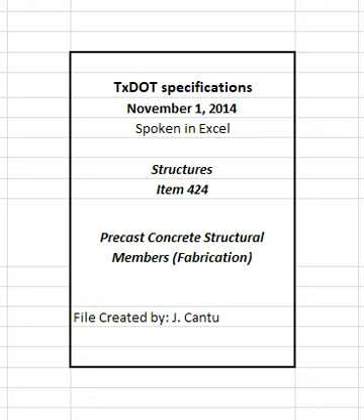4.2.7.4 Accelerated curing. Accelerated curing is defined as curing with artificial heat provided to the curing enclosure or forms. Test accelerated curing facilities for a minimum of 48 hours to demonstrate temperature variations do not exceed 20 degrees Fahrenheit between any points in the curing enclosure. Submit accelerated curing facility drawings and test results, and obtain approval before using these facilities for department work.